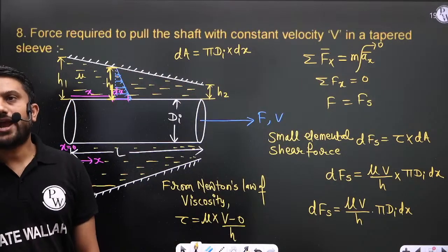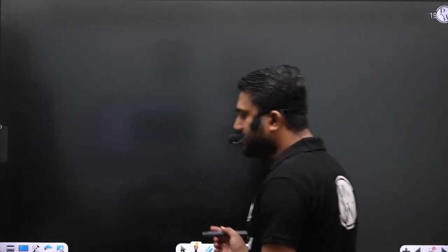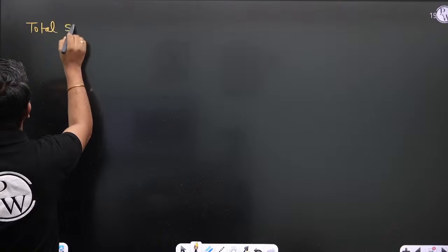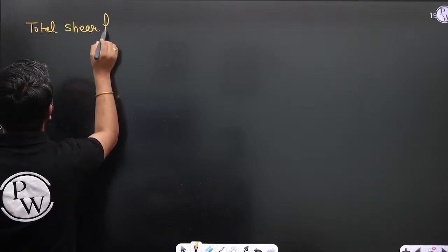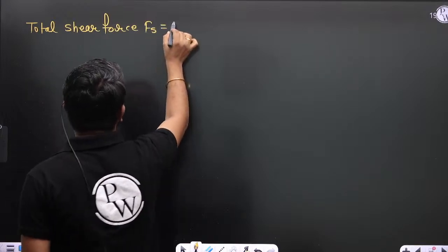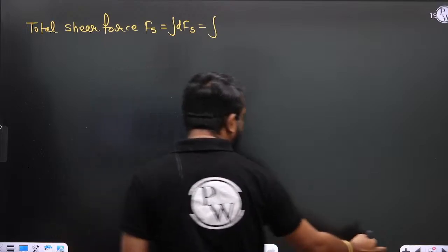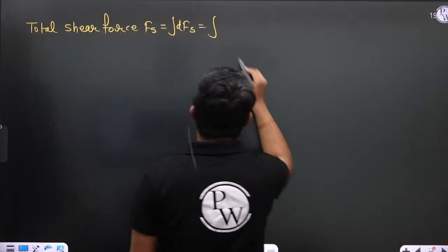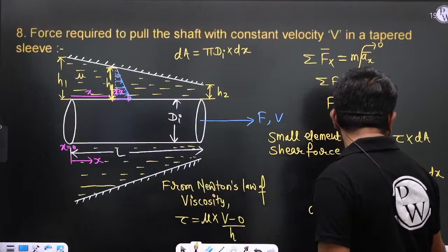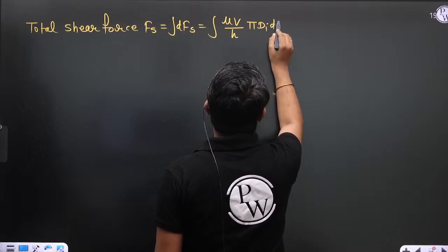But I want to calculate the total shear force. So what is the total shear force? It is simply the integration of dFs, that is the integral of mu V by h into pi d_i dx.